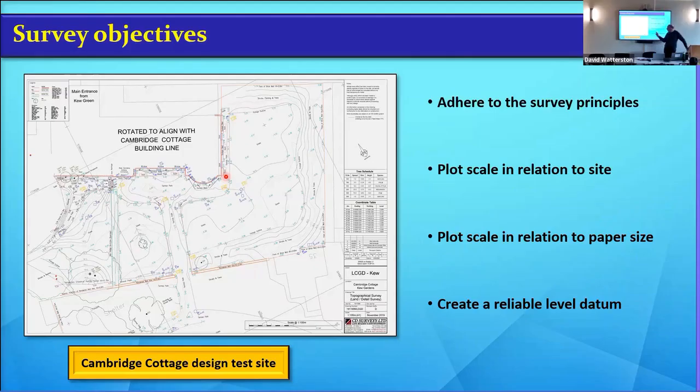But you might want areas that are bigger. But the trouble is, if you get 1 to 50 or 1 to 20 surveys, which is fine, you like using it because in a small garden it's great and you can see what you're doing, you can measure things, and you can put your little plants in, and it's all lovely. When you then go to a bigger survey and you say, hang about, I quite like that 1 to 20 scale or 1 to 50, and it's that size, you're going to end up with multi-sheets.